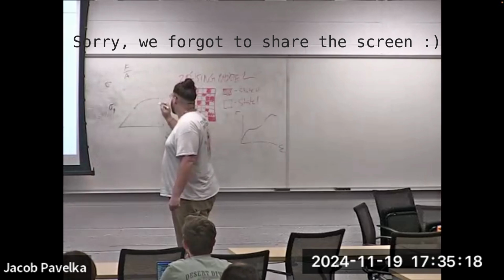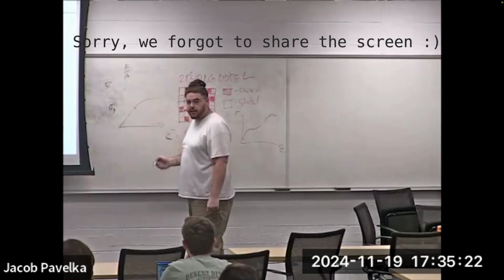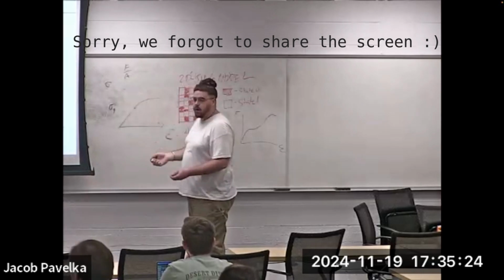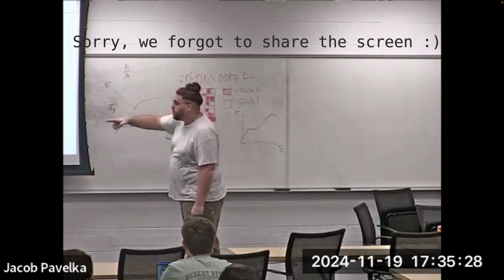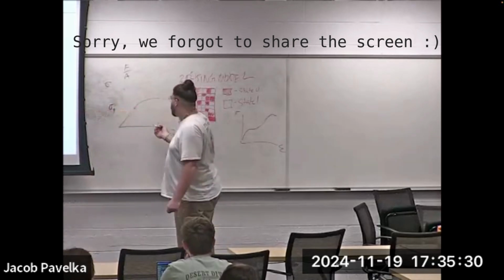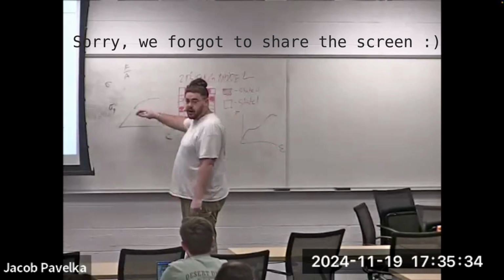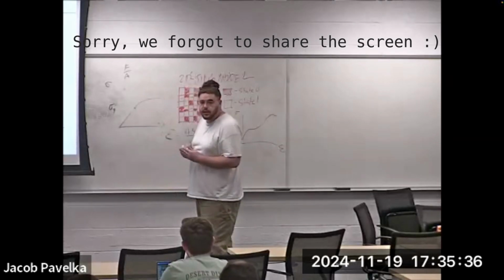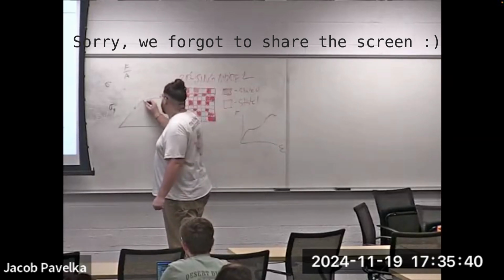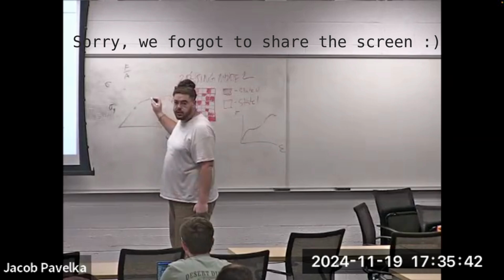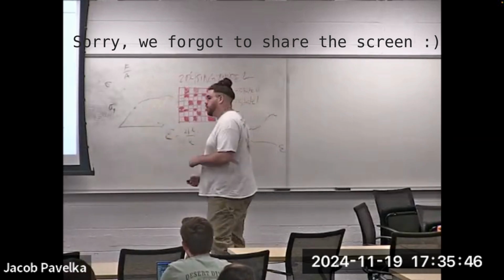And there are many different models for this nonlinear behavior, but one is the linear hardening model, with this strain hardening exponent, washing over a lot of things, but generally it just characterizes how this nonlinear behavior forms. And you call it strain hardening basically because this slope is getting stiffer progressively. So the material is getting harder to deform.